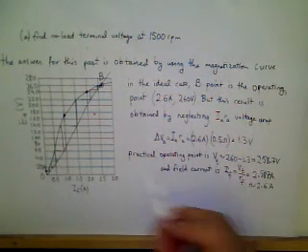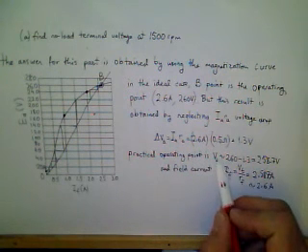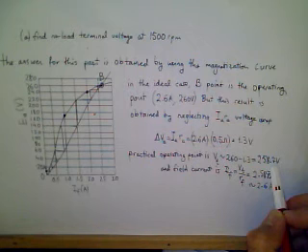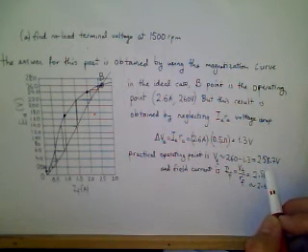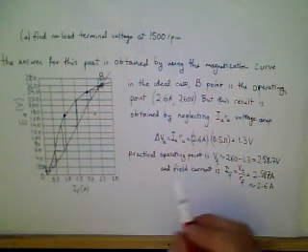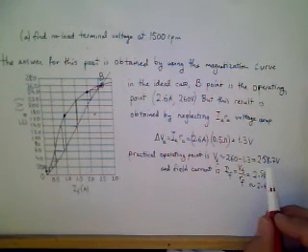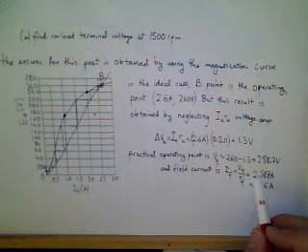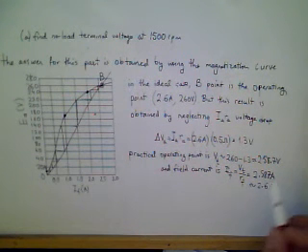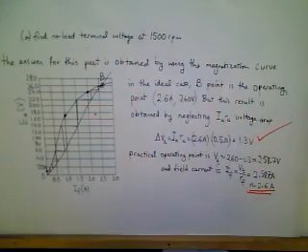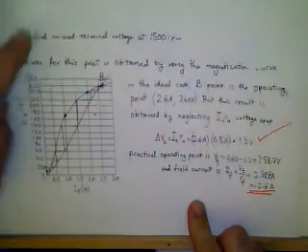Neglecting it could be okay. In practice, the operating point is roughly 258.7 volts. So this is the terminal voltage considering the armature voltage drop, and that terminal voltage will create a field current of about 2.587 amps, or roughly 2.6 amps. So our neglection is okay. We don't make much error.